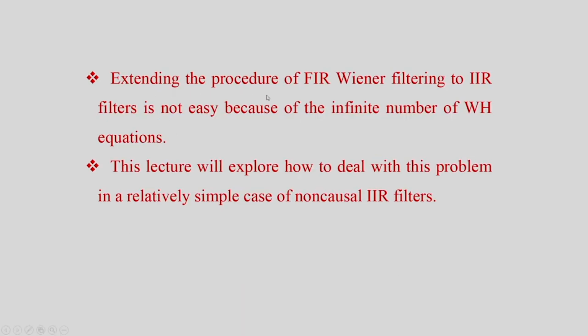Extending the procedure of FIR Wiener filtering to IIR filters is not easy because of the infinite number of Wiener-Hopf equations. So, we do not have any way to solve the infinite number of Wiener-Hopf equations in the time domain. This lecture will explore how to deal with the problem in a relatively simple case of non-causal IIR filters.